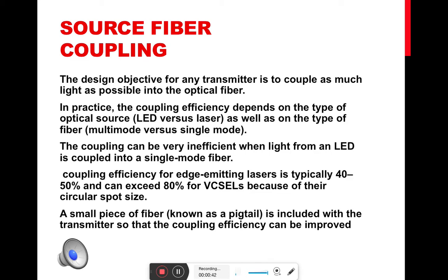So the coupling can be very inefficient when the light from an LED is coupled to a single mode fiber. As you all know, there are different wavelengths of light that are coming from an LED. So LEDs are not a good option for single mode fibers. LEDs are always used with multi-mode fiber. So when you are coupling an LED with a single mode fiber, there are chances that most of the light from the information source gets leaked off.